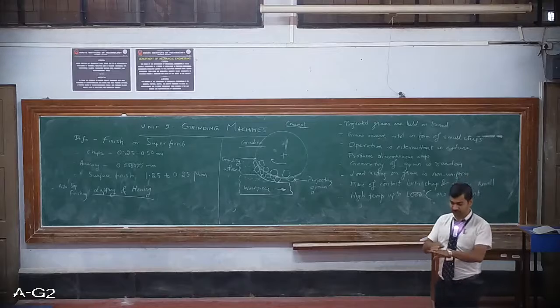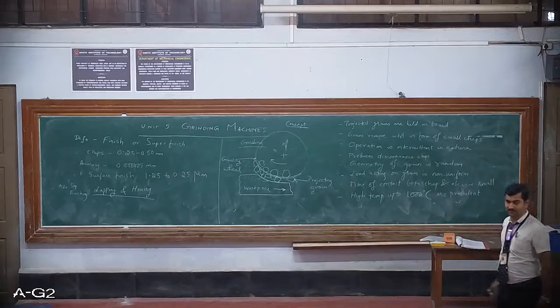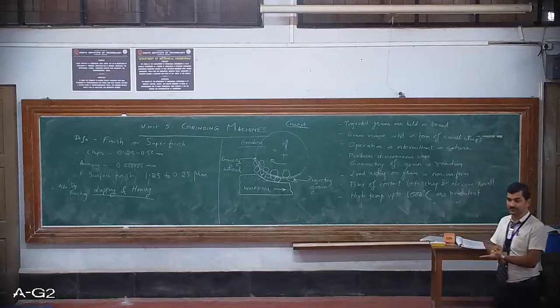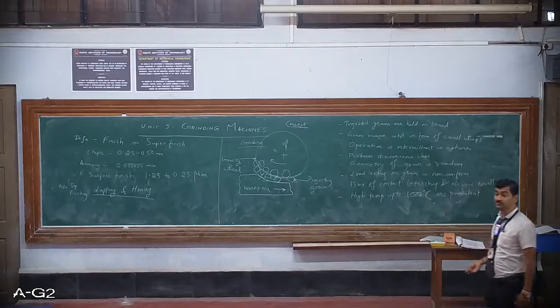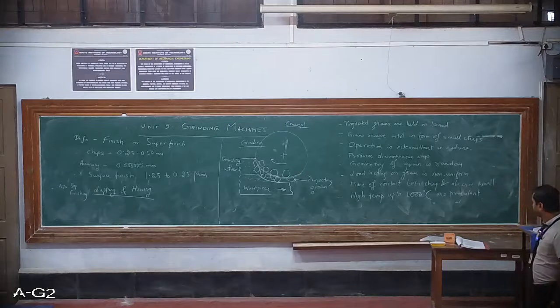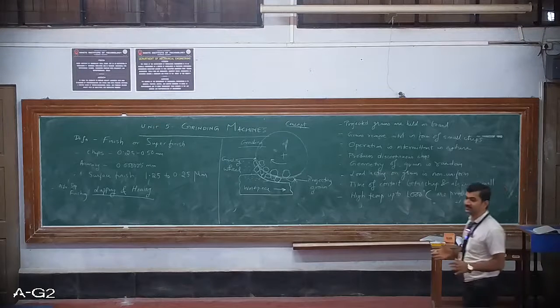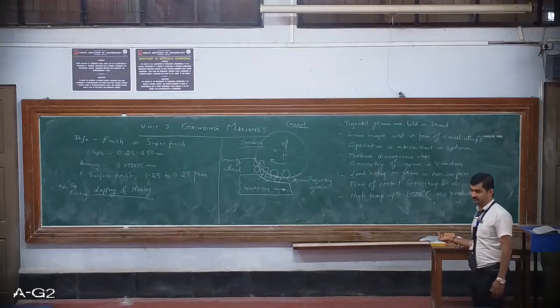It's like sandpaper you take and just try to remove the paint. If you just scratch it on your fingers, you will bleed, right? So that is how the abrasives work. Next, the high temperatures. Because of this rubbing action, there is high temperature that is prevalent at the work tool interface.